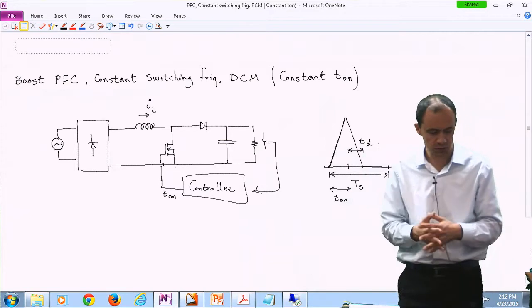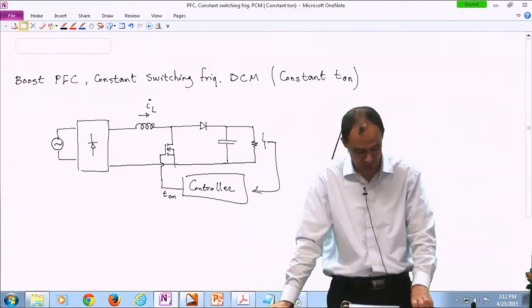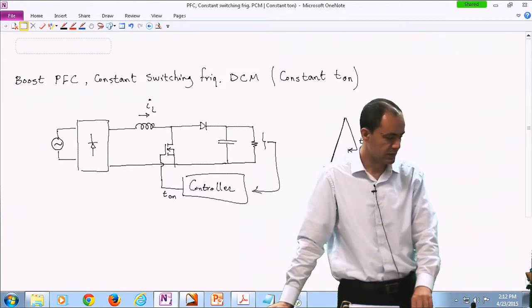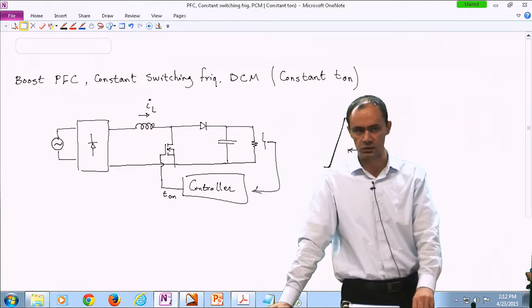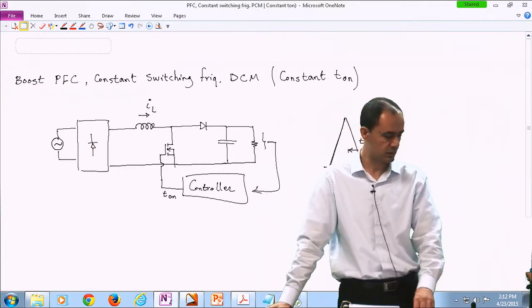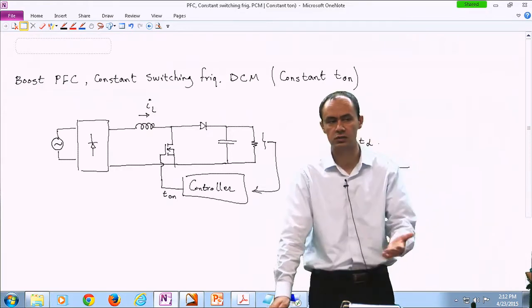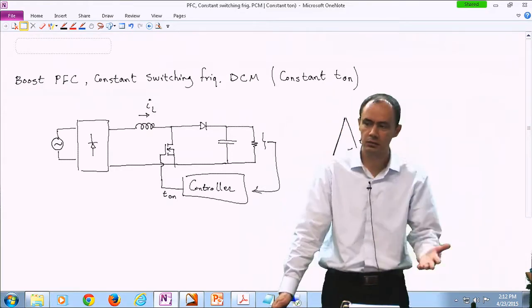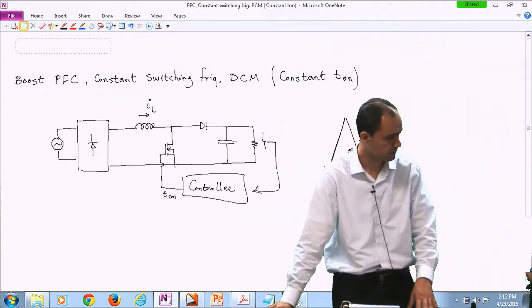And we haven't talked about soft switching yet, but this is going to be our last topic after PFCs are over. So we realize that whenever you turn the switch on or off, if the current of the switch is starting from zero or returning back to zero at the very same time, it's good. That means your current doesn't jump, there is no di/dt, there is no EMI noise, it doesn't couple with the leakage inductances and things like that.